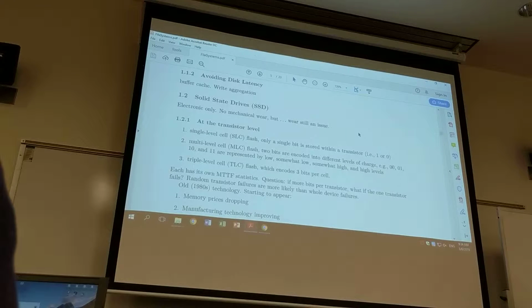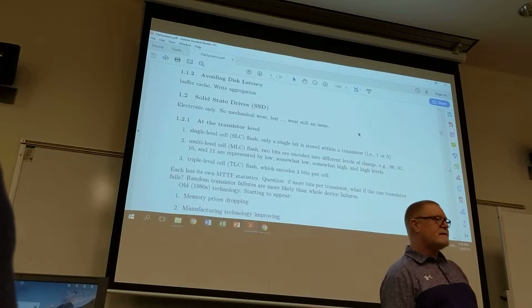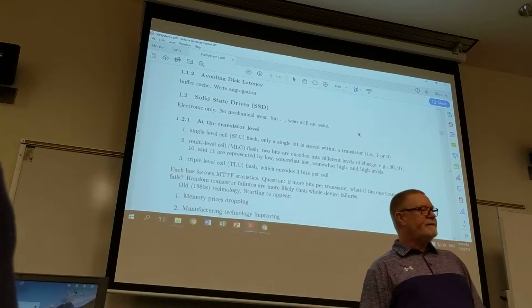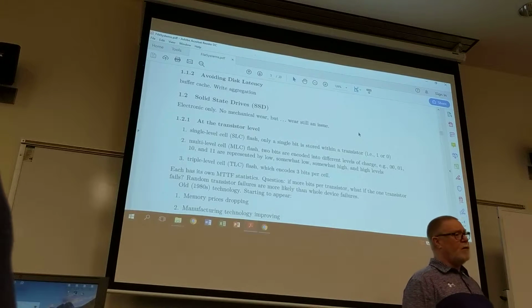But it's still there. That's why oil breaks down and things like that. We'd rather have the oil breaking down and costing us $50 to change than the bearings breaking and costing us $3,000 to fix the bearing. But friction is still there. There is a lifetime. For almost all discs these days, the lifetime is until the bearings fail in some way.